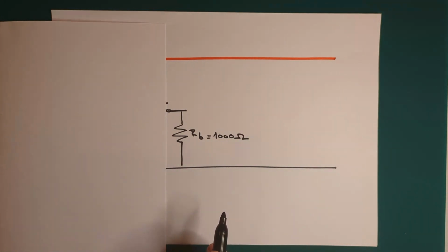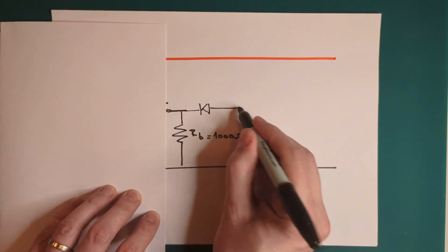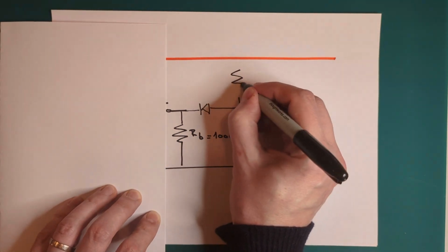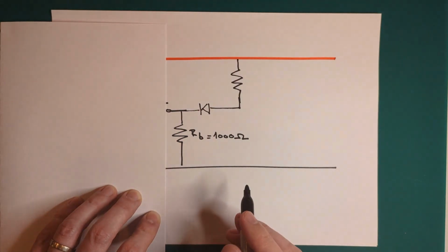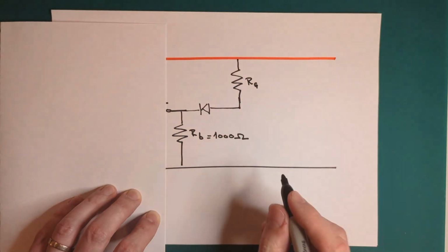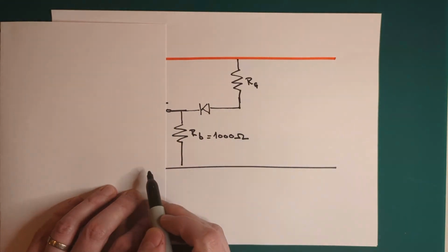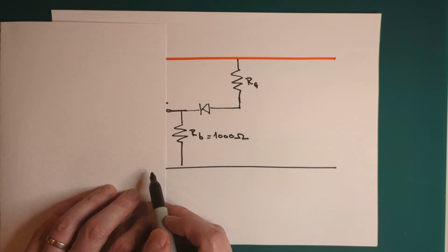Now let's link to our gate, which is the diode, and this resistor here going up to my 5 volts rail. So this gate resistor is, again, to prevent the short if I connect the input directly to 0 volts, which is something that should be allowed.